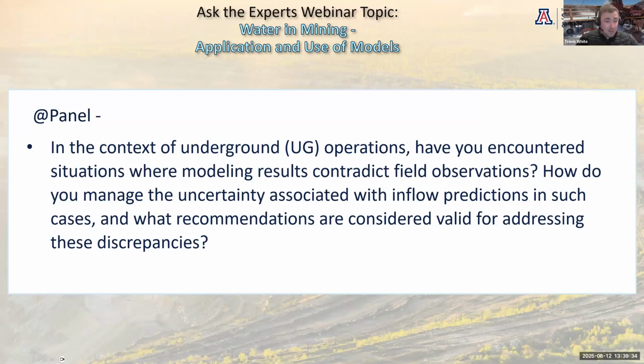Yeah, this is exactly why you should never just trust the model. You should look at everything holistically. Yes, it's happened to me before and happened many times. Well, I'm sure to most people. How do you deal with it? Look, what we do as a standard when we design the underground water handling capacity, we typically scale it up to 200% of the requirements. That's for a few reasons. Number one, in case your model's wrong and you haven't looked at everything else. Number two, water handling systems don't operate at 100% utilization or availability. So that's the redundancy that you build in there.